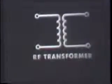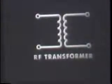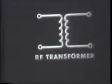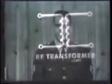The schematic symbol for an RF transformer, then, is easily identified by there being no vertical lines between the primary and the secondary coils. Now, a special type of transformer which uses only one winding for both the primary and the secondary coils is the auto transformer. In addition, an auto transformer can be used either as a step-up or as a step-down transformer.